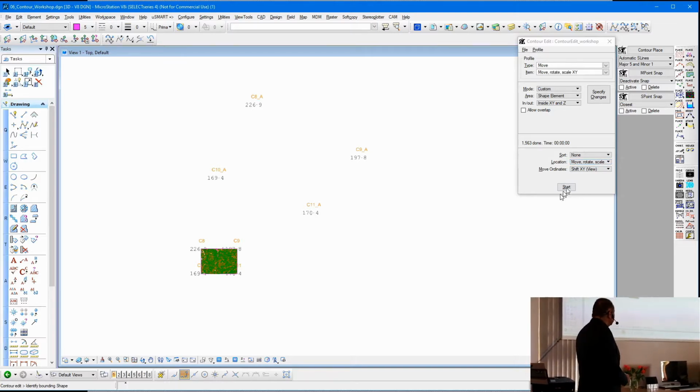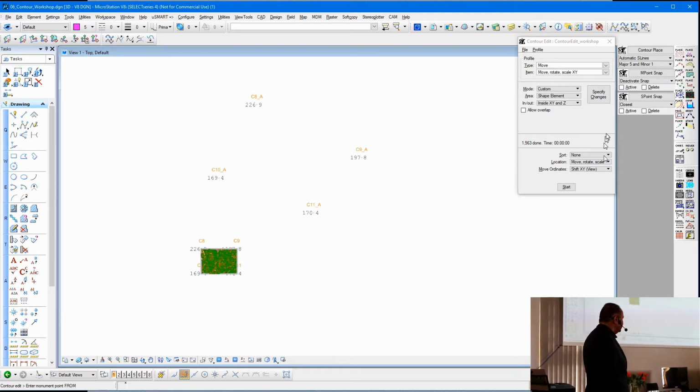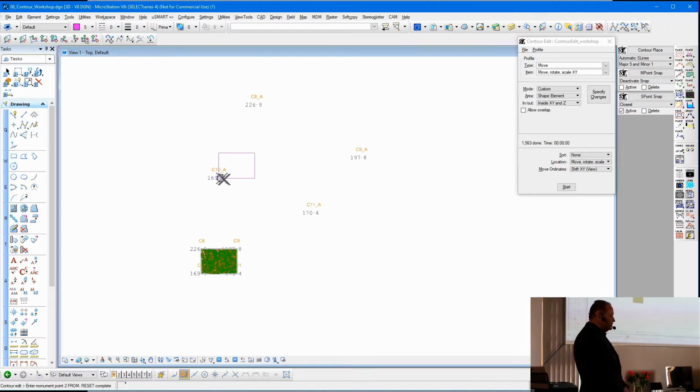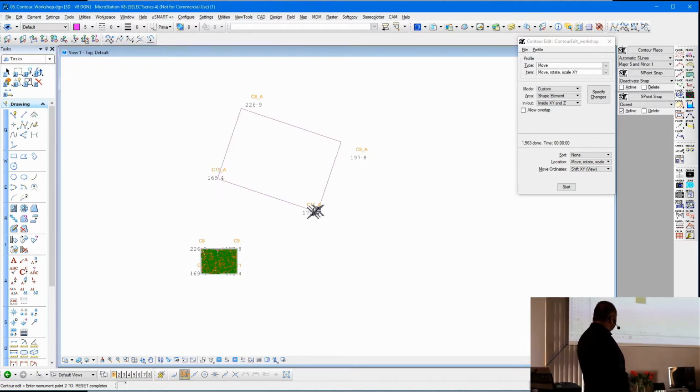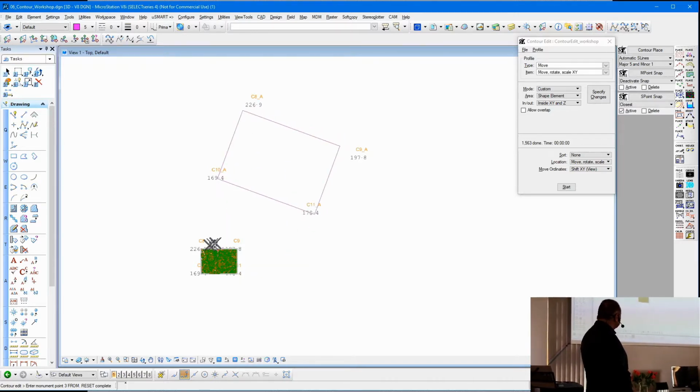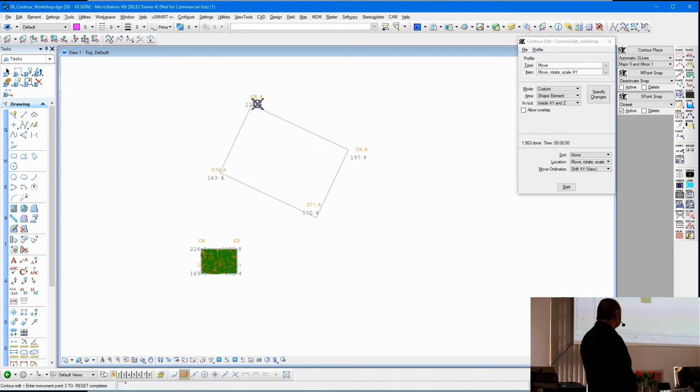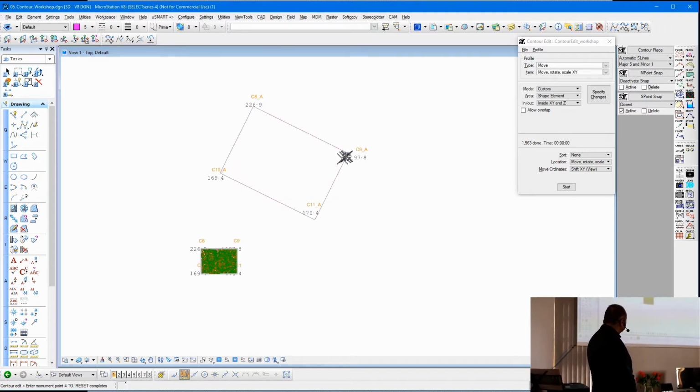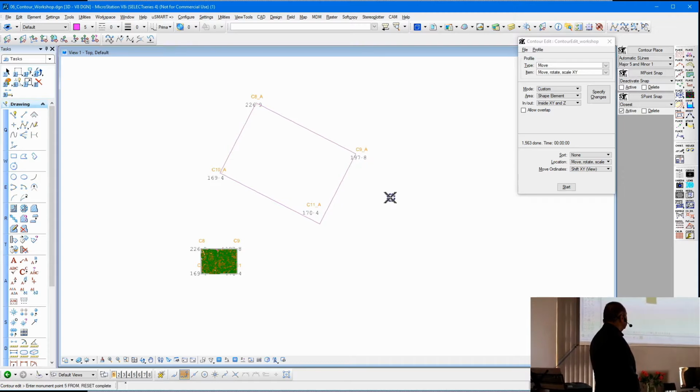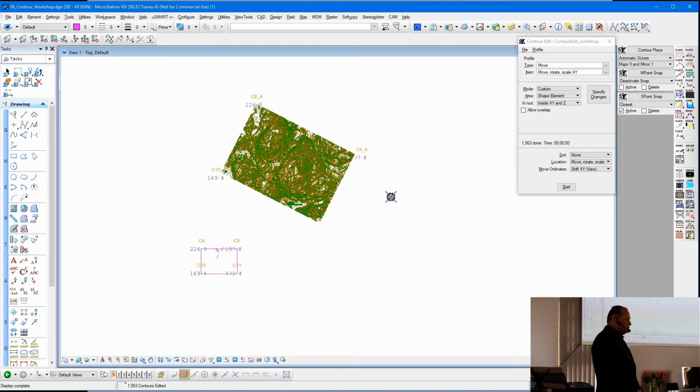So now we're going to say, okay, first of all, that's the area, choose the area, Corin's chosen the area. Then it says, enter monument point from. Always read those things at the bottom. Some people put them at the top. Enter monument point from, and she says, okay, well, that's my other point that's on the other system. And now enter the second monument point. So this is if you just want to quickly move things onto your, and the third, and you just keep on going, as many as you have. And when you press reset, it gives you the results. So it gives you best fit.